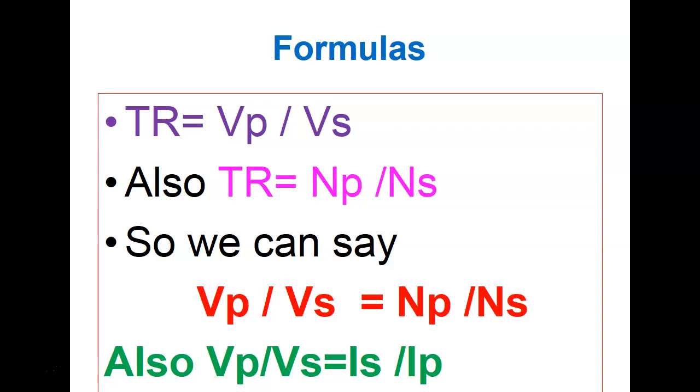By the way, these guys have a lot of wire. They have a lot of resistance. And if you have a transformer and you have all the same transformers, you could get your own meter and record the primary resistance and the secondary resistance somewhere, and you can check them with an ohm meter after that. So that's basically what we do. We've got a good transformer. We measured that, and we've got a transformer that's not working. We just measure the ohm values, and we can tell if the ohm value is a lot less, it means it's got shorted windings in it, right?